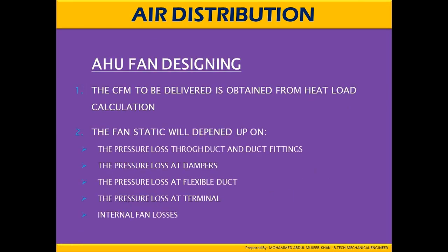AHU fan designing. The CFM to be delivered is obtained from the heat load calculation. The fan static will depend upon the pressure loss through duct and duct fittings, the pressure loss at damper, the pressure loss at flexible duct, the pressure loss at terminals, and internal fan losses.